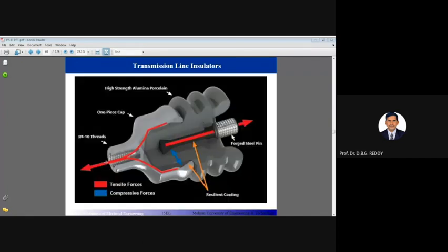Now this is the cross-sectional view of a conductor. While carrying the overhead transmission line, we use a high-quality insulator at any cost, because the structure is steel. If the wire touches it, leakage current and power loss will take place. We have to use a high-quality insulator to carry the power safely from the generating station to the load center with minimum losses.